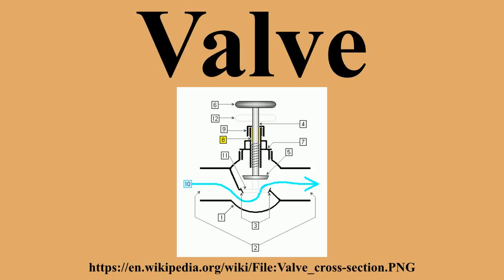Ball valves use spherical rotors with a cylindrical hole drilled as a fluid passage. Plug valves use cylindrical or conically tapered rotors called plugs. Other round shapes for rotors are possible as well in rotor valves, as long as the rotor can be turned inside the valve body. However, not all round or spherical discs are rotors. For example, a ball-check valve uses the ball to block reverse flow, but is not a rotor because operating the valve does not involve rotation of the ball.